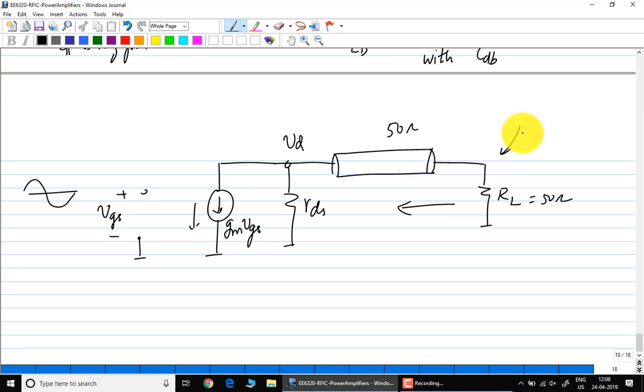This is anyway connected to the antenna, right? The antenna might receive some junk while you are transmitting. What is going to happen to that junk? That junk is going to come in, right? Now that junk is going to get multiplied by the standing wave ratio to give you a large drain voltage. So the point is, you do this to prevent the PA from getting disturbed. You do output matching to make sure that the PA conditions are well defined.